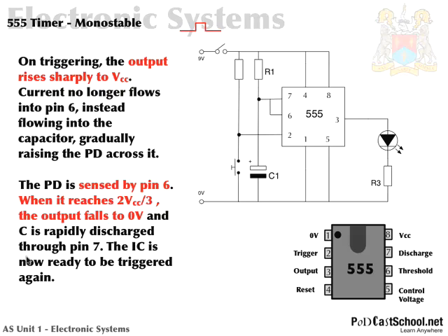So really all this is the pins on the IC changing their input impedance or input resistance, you can think of it as. In one state, before it was triggered, 6 has a very low impedance and current flows directly through the IC and down to ground through 6.